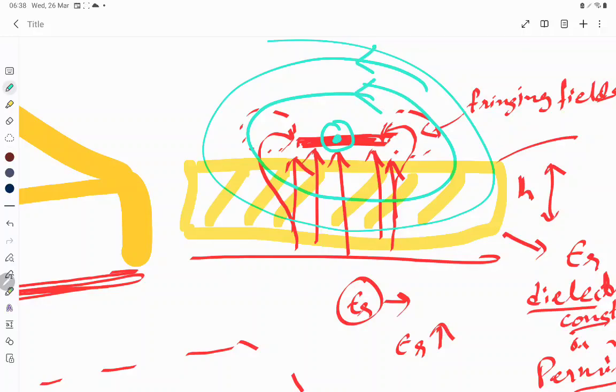So here also mostly the electric fields and magnetic fields are perpendicular, orthogonal to the direction of propagation. So this is almost TEM. It is not perfectly TEM. Maybe on some other occasion we shall talk about why it is not completely TEM. But this is called quasi-TEM, or almost TEM. It almost behaves like the TEM wave.